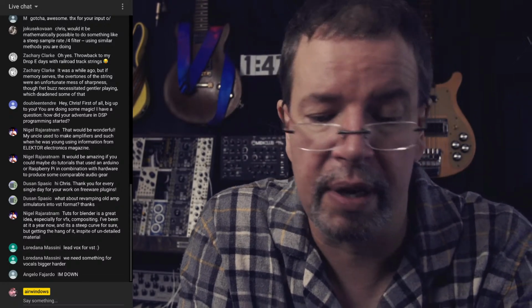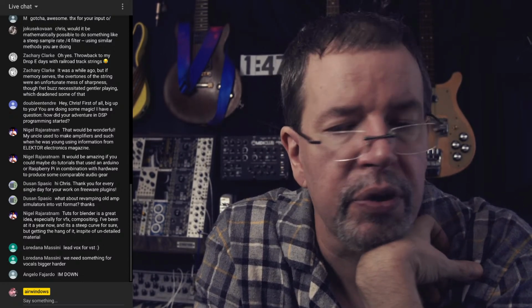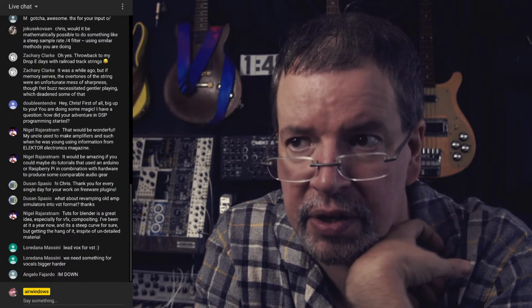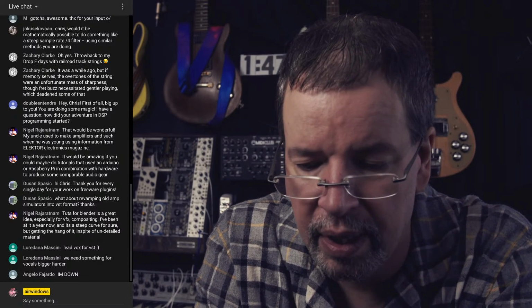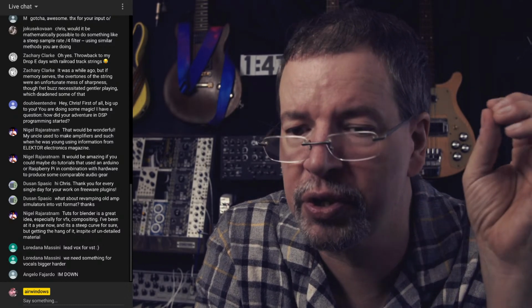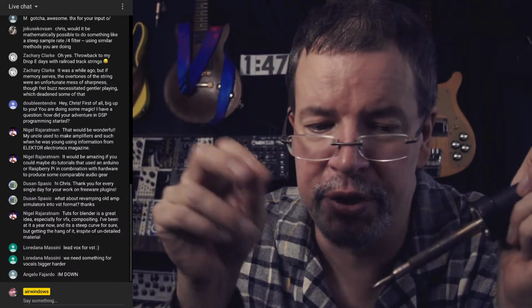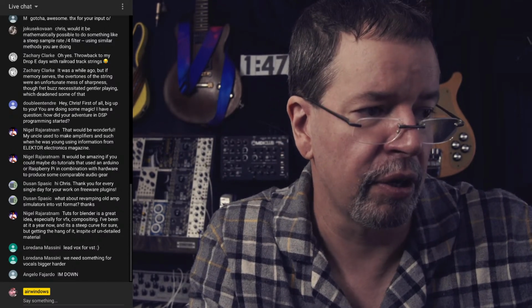Certainly some of the things that I'm going to need to do is have enough of a close-up available so that I can solder connections and show you how that's done, because I've seen people soldering on YouTube that did not know what they were doing. And they were doing stuff like, okay, I squish the soldering iron into wherever and then melt some solder off of the soldering iron and drip it onto the thing. And it's like, that ain't how that goes.